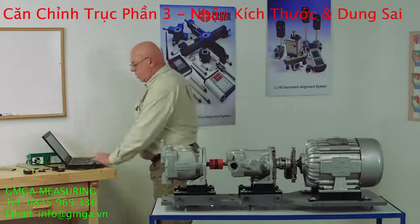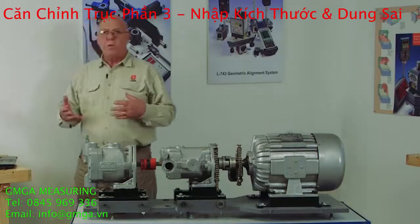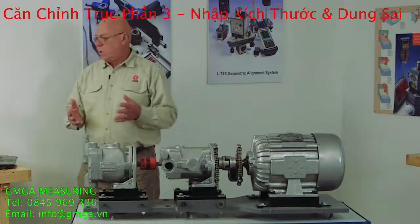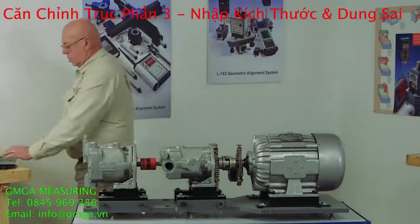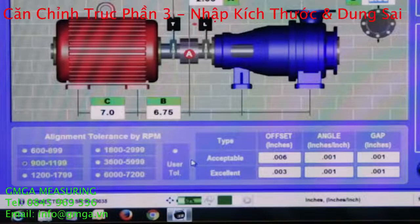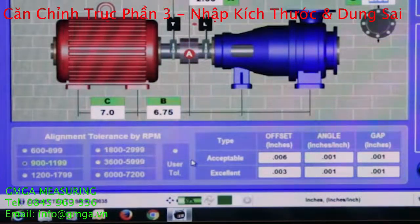Now we have some tolerances. And we have a chart down here, alignment tolerance by RPM. This is a standard chart that we're not the only ones that use it. It's common, it comes out of Machinery Handbook, I believe. So basically, if the motor is turning, in this case, 900 to 1199 RPMs, these are our tolerances over here. We have acceptable tolerances and we have excellent.